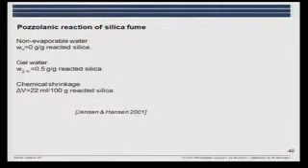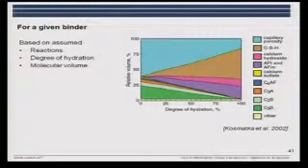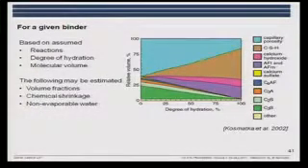This model, the Powers model, could be improved if we knew more about the cement reacting. If we have information on the reactions taking place, the degree of hydration, and the molecular volume, we know the volume of the hydrates, and we know the composition of the material, we can actually estimate the volume fractions, the chemical shrinkage, the non-evaporable water.